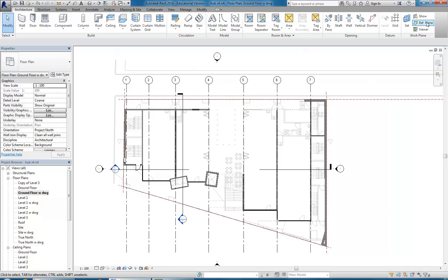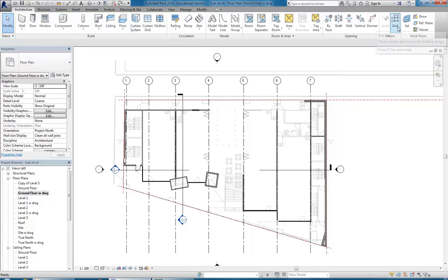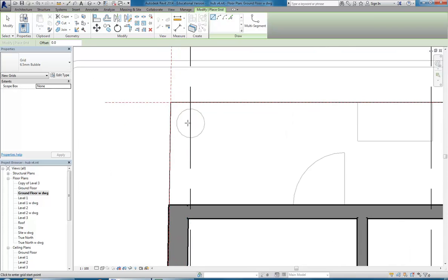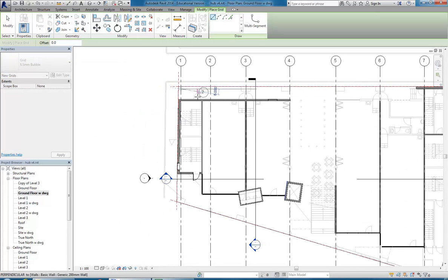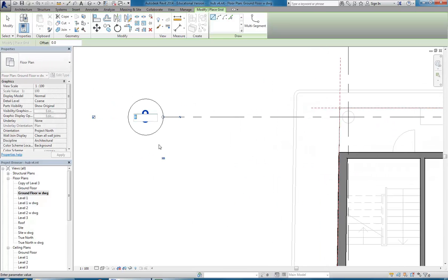And so then going the other direction, I'm just going to go back to the grid tool, and then going to the center point of this column, of this circle, I'll type SC to force it, and I'll take this grid, I'll do it over on the left, and I'll stretch it out to the right, and you can have letters as well as numbers for your grid bubbles.